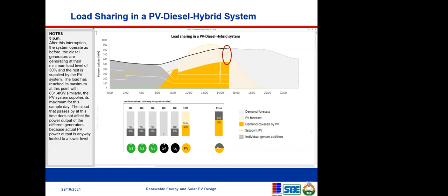There is special equipment to harmonize them. Of course, if you're having a hybrid system, those are the special features that they have. Because in power generation, when power is coming from different sources, we have a synchronoscope that will check the voltage and current at each one before connecting. Exactly, that's what I'm saying. So that's the special feature that hybrid inverters have. They have those characteristics to be able to do that. Okay, thank you.